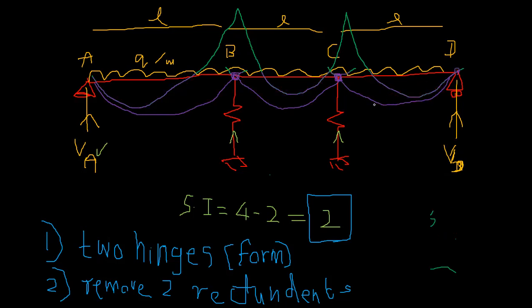Here also it's changing, but we are only worried about the joints, right? Because that's what we need to solve at the joints. So here you didn't change. That's okay. But here it was initially some value, then it's 0. So you bring it to 0. So you make the bending moment 0, such that it is no longer your original structure, right? So we can go ahead and this is our primary structure, right?